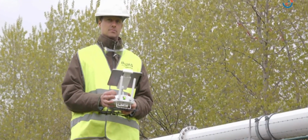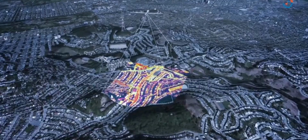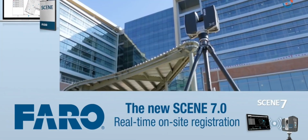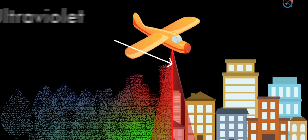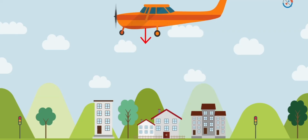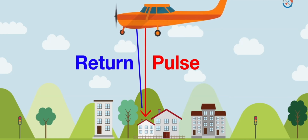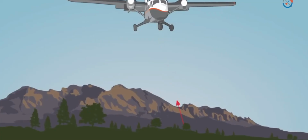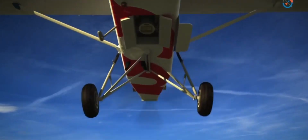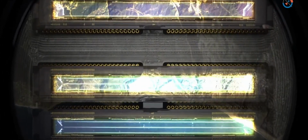To detect objects, lidar employs an ultraviolet, visible, or near-infrared source. Light energy released by a lidar system is known as pulse light, while light energy reflected off the ground or an object is known as return light. This means that the lidar system sends a light pulse and then waits for the pulse to return. It determines the varying distance of the objects by measuring how long it takes for the transmitted pulse to return to the sensor. Actually, this is where the name lidar comes from, light detection and ranging.